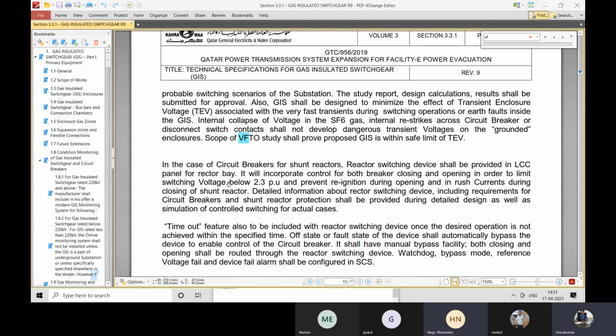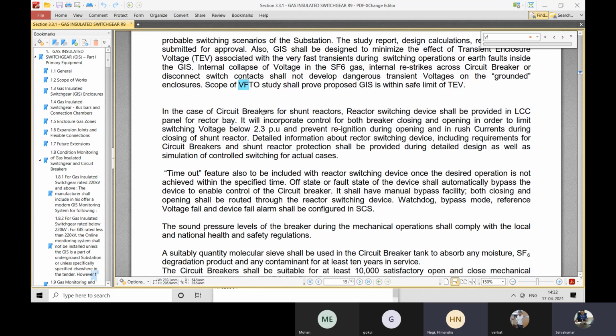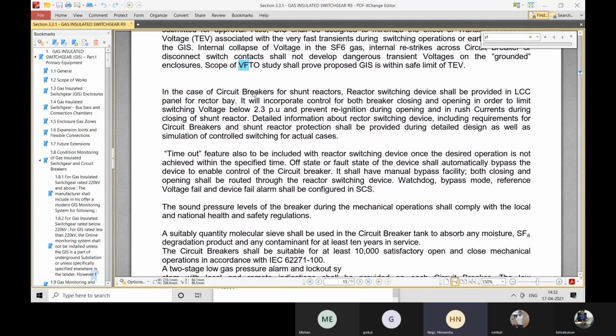Yeah, right. So you will not model anything of the GIS equipment in CDEGS then. No, it's not possible. Whoever is telling you these things, it's just a myth because they just made it up. There is no way to model any of the devices other than the conductor.